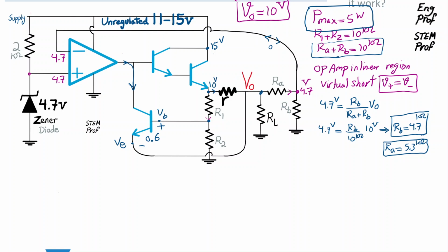So 10 volt basically here, and then that means we have about 5 volt drop across the collector and emitter of transistor, let's say T1, and this is T2, and this one is T3. So what I can say, power of T1 max, which is the dominant power consumption in the circuit, is limited to 5 watt. For one scenario, which is nominal operation, when output is 10 volt, we can see it's max,